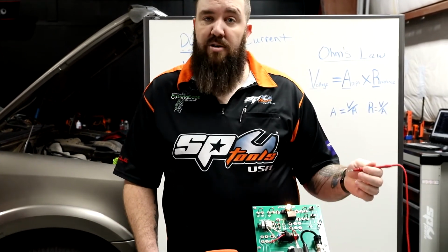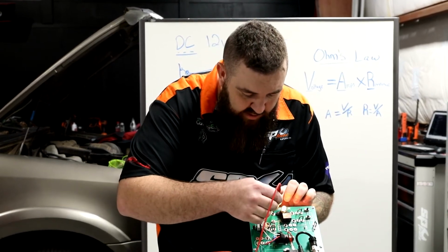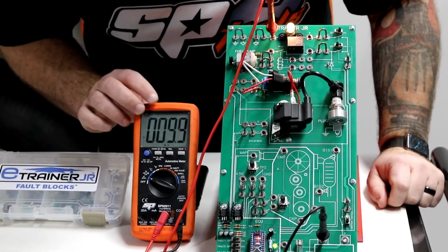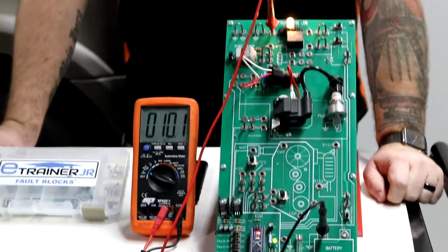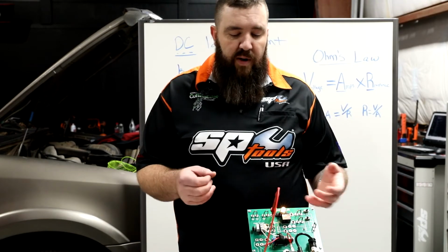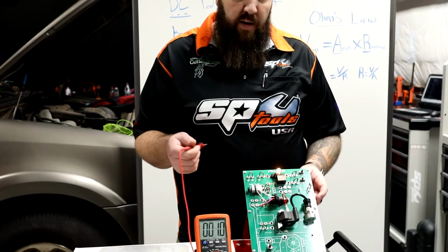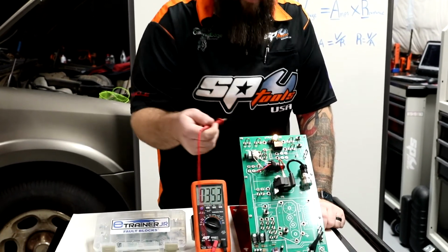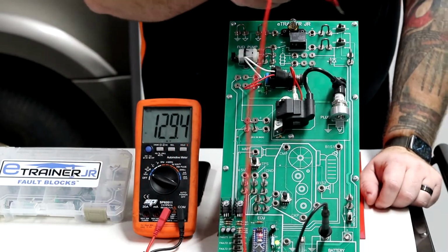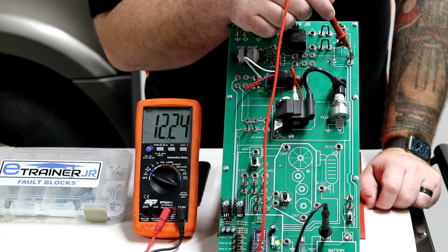So, how much of that voltage is the system going to be using? We test right after our little light bulb, and we can see we have right at about 10 volts. Now, when you're testing electrical circuits inside of a vehicle, you want to test for voltage at certain points. Say for some reason this light bulb was not working, you can test at the battery. Yes, we have good active voltage right there. And then you can test just before your switch, where you can tell we have full 12 volts.